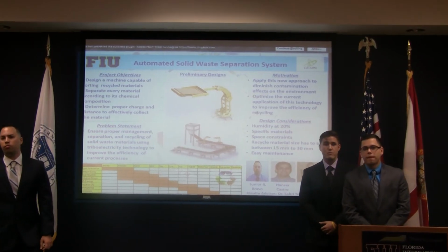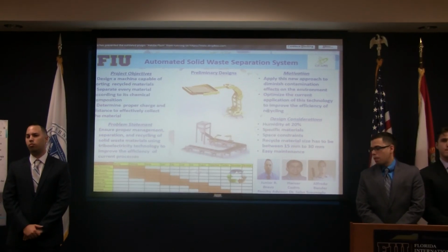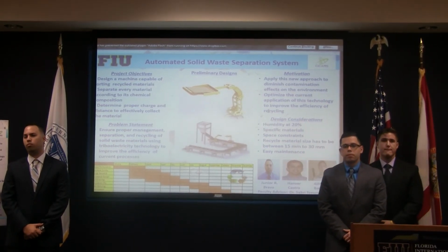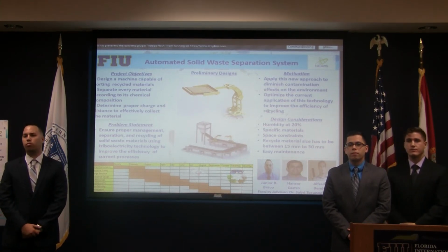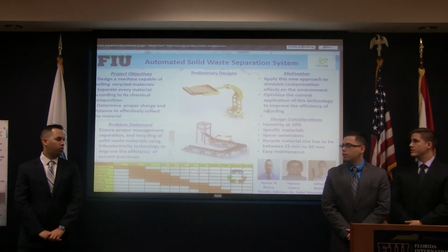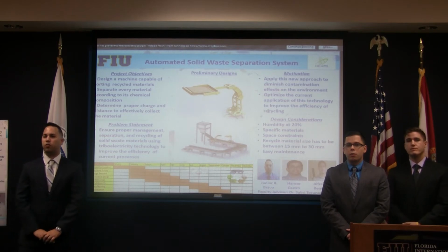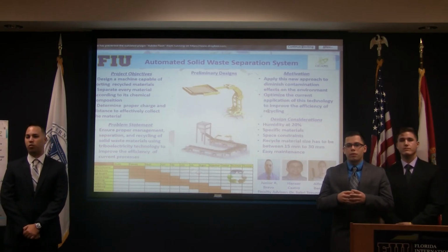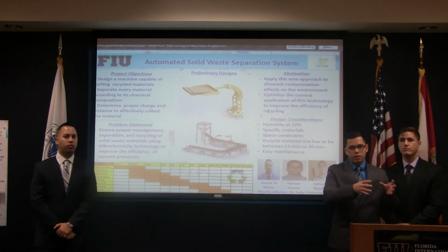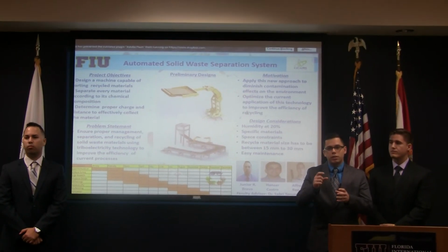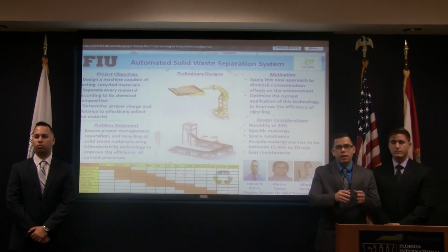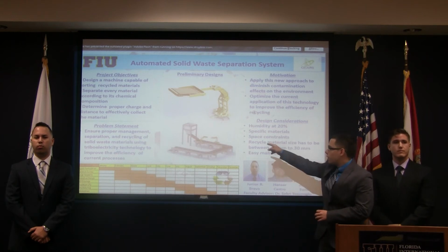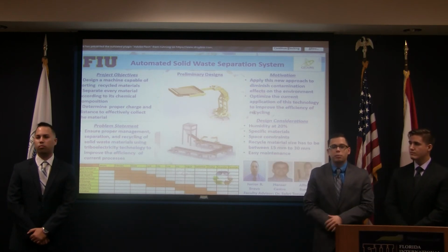Yes, go ahead. So the design does include this part, both systems are inclusive of this project, right? The crushing or the sizing of the proper bulk material and the separation? Or are you just concentrating on the separation portion? Just the separation. Just the recycling of those 4 different materials. That's what we're concentrating on. The other system is going to be drying the material and crushing the material between 15 millimeters and 30 millimeters. Once the material is dry and crushed, then it comes here to the separation process.